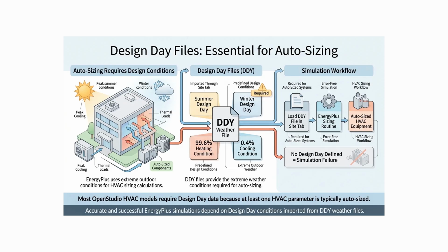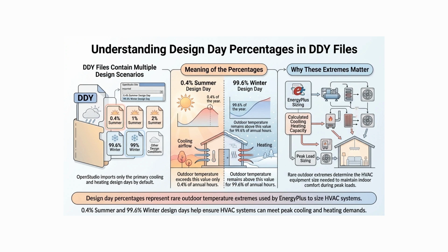You may remember from previous lessons that DDY files are imported through the Site tab. When you load one of these files, OpenStudio brings in a set of predefined design day conditions. A typical DDY file includes several different design scenarios, representing a range of heating and cooling extremes. However, OpenStudio imports only two of these by default: the 0.4% summer design day and the 99.6% winter design day.